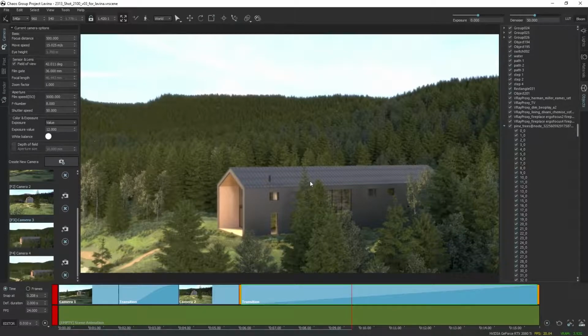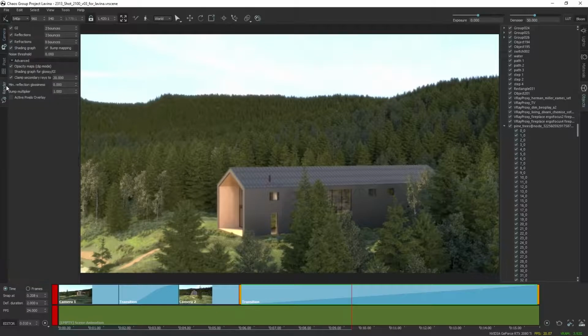Okay, I think I have a little bit of time to quickly mention the other quality setting that we also added in the last version of Lavina, and that's located in the render settings, and that's the noise threshold. The noise threshold actually introduces adaptive sampling, which means that some pixels are going to be sampled more or rendered with higher quality, while others that do not need it, such as the background or flat surfaces, will not be. Lavina will not spend too much time rendering those.